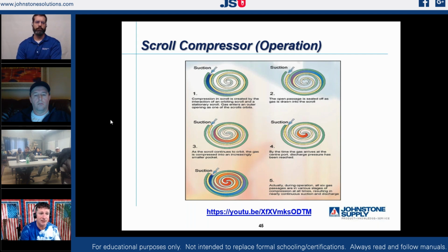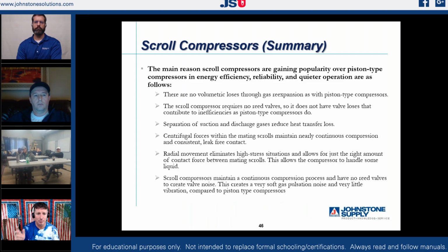And so instead of just having that positive and negative displacement on the reciprocating compressor, we now have fairly even distribution across our pump. So our centrifugal motion isn't offset. Because if you think about that, if I've got a 2-cylinder reciprocating compressor, I have all sorts of momentum going back and forth, right? Which is putting a lot of resistance on my motor. If I have multiple compression strokes inside of that compressor, I'm actually distributing it more evenly. So I don't have as much reciprocal energy going on as what I had in a reciprocating compressor. So a lot less energy to move our vapor pump.